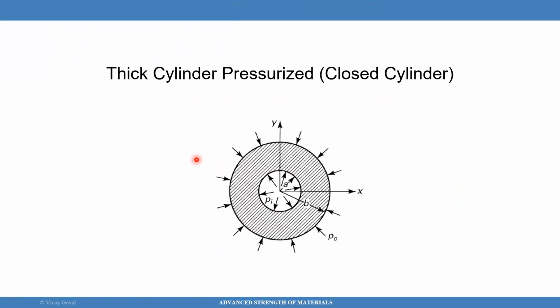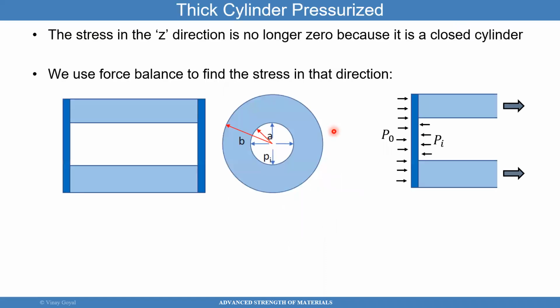Okay, so now I'll move to thick cylinders, but they're closed. So the pressure now is applied, but now the cylinder is closed. So now that pressure reacts against the end caps. Okay, so let's look at the case of the closed cylinder. In a closed cylinder, what you really have now is like a can, a Coke can, right? Or Sprite, whatever you prefer. I'll say Pepsi just to cover everybody. But if you have a cylinder that's pressurized, it's going to react against this wall. You agree? But if you have pressure outside also, then you're going to have pressure in these caps too.